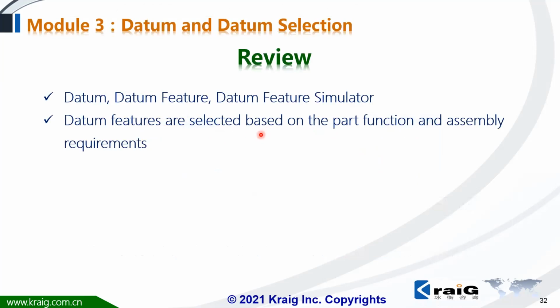All right, let's have a quick review about Module 3. In this module, we explained very important key terminology. What is datum? What is datum feature? And the datum feature simulator. And we also explained the principle. How could we select the datum feature? Should be based on the function of the parts or based on the assembly relationship.